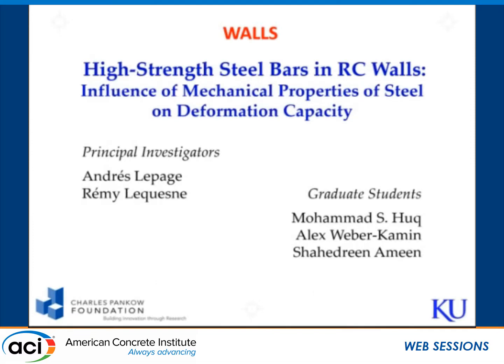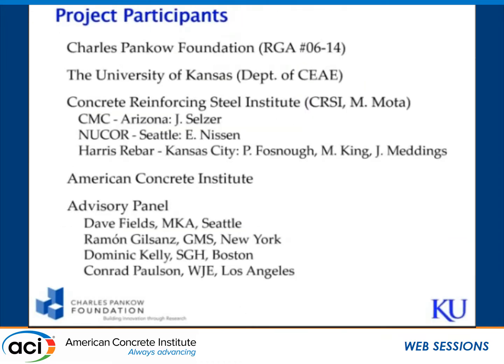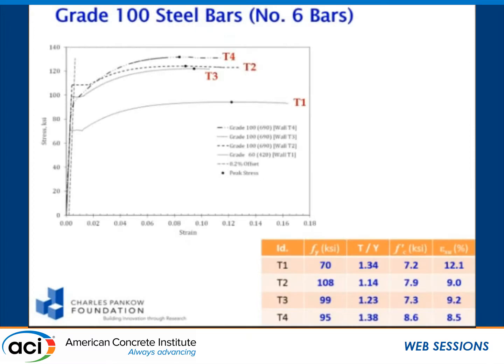On the wall side, Andres Lepage and Remy Lequen up in Kansas looked at walls. The interesting thing about walls is they will develop high strain demands. Because the sections are so big, you are going to get big strain demands on those bars. So that was an interesting project. This is sponsored by Pankow Foundation, supported by CRSI members and CRSI and the advisory panel on that project. They also looked at the equivalent of what the columns and the beams did, but for the walls. So same thing, 4 walls.